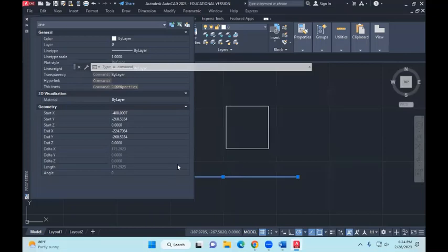Now let's try to change the weight of the line. Let's try to make it thicker, or change the line thickness. Somewhere you will see line weight. It says line weight over here. It starts with color. You can even change the color of the lines. By default it's white because it has a black background, right? So you have a white line color by default. You have line types, line type scale, all the other things.